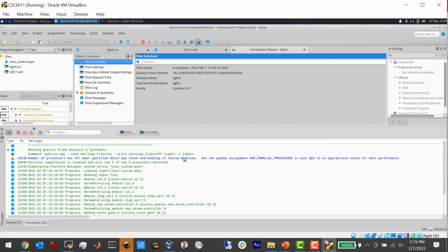Okay, now you'll notice that the tools are slow. This slowness is understandable though, because it's actually building the actual gates. It has to parse the SystemVerilog, convert it to a netlist, which is a graph of logic gates, and then map each of those logic gates onto the physical gates on the FPGA and then form connections between them. It takes a long time.